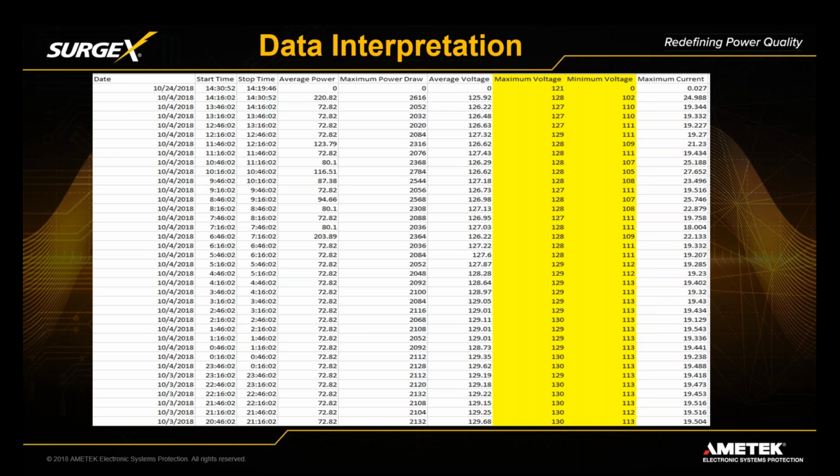conductor. And what's happening during those periods is you've got some equipment, like let's say it's a residence, and you've got a 120/240 center tap service, and you basically have the two 120 volt circuits coming off of the same transformer. Well, if the neutral connection is bad, either missing completely or just loose in a high impedance, what you'll see is stuff like you turn on heavy loads, and you might see lights flicker, weird things like that, and basically the voltage will start dividing itself differently between the two circuits, where sometimes it's going to be higher on circuit A while it's lower on B, and then if the loading changes, now it'll be lower on A and higher on B, that sort of thing.